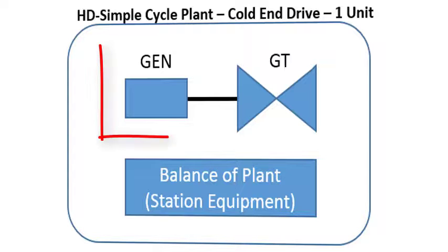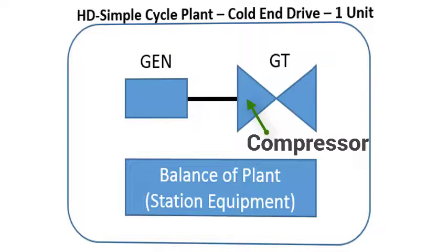The generator is shown on the cold end, the inlet air end, in front of the turbine's compressor, out of the hot exhaust, an exhaust temperature that can exceed 800 and could go up to 1200 degrees Fahrenheit. A combined cycle power plant needs 1000 degrees exhaust temperature to create high temperature steam.